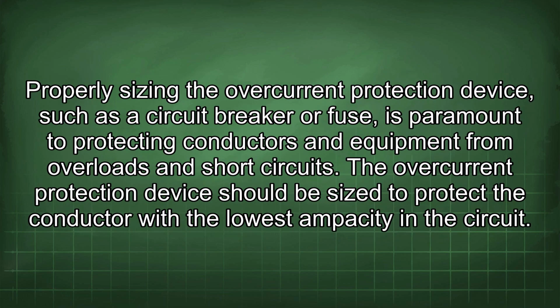Properly sizing the overcurrent protection device, such as a circuit breaker or fuse, is paramount to protecting conductors and equipment from overloads and short circuits. The overcurrent protection device should be sized to protect the conductor with the lowest ampacity in the circuit.